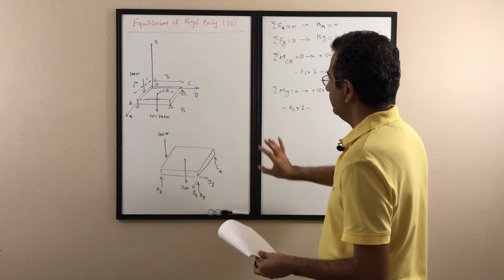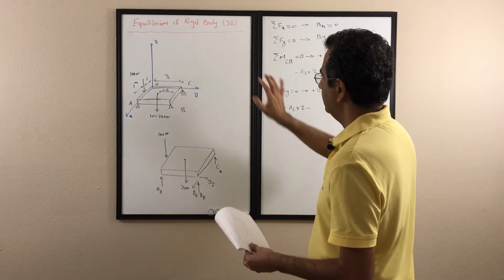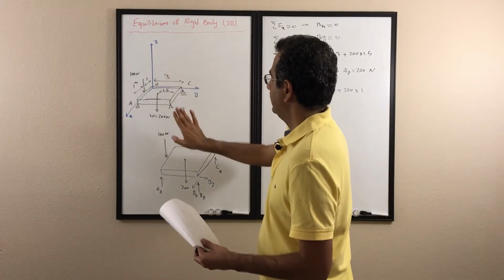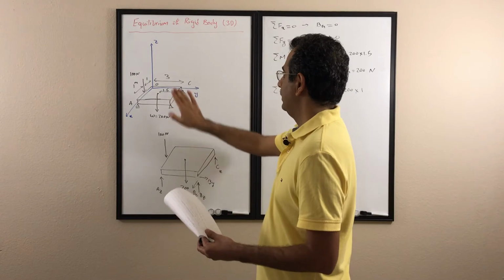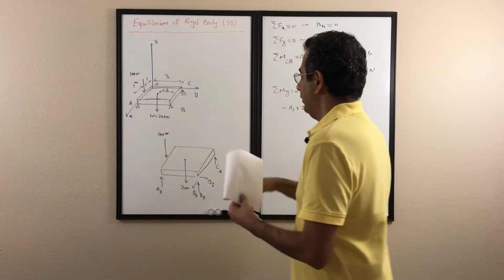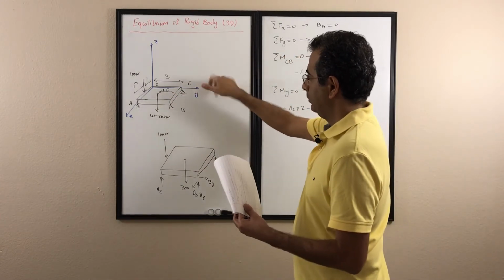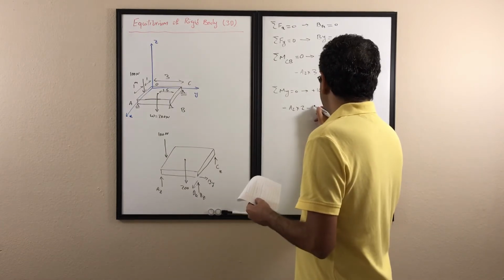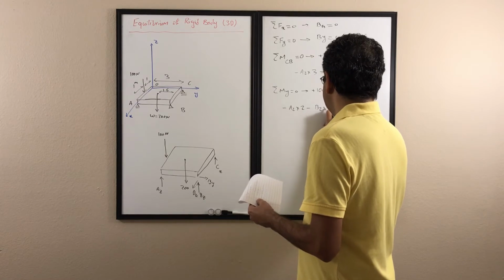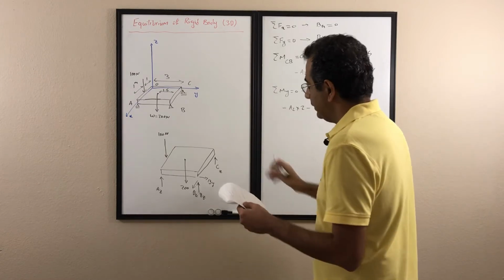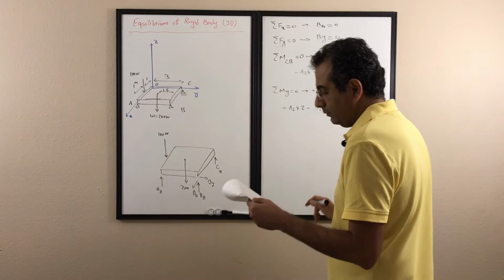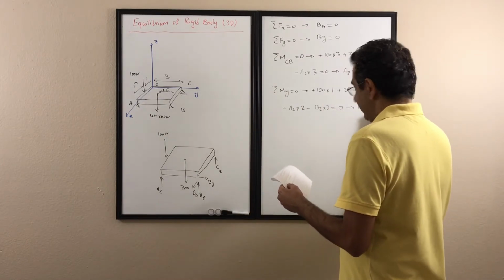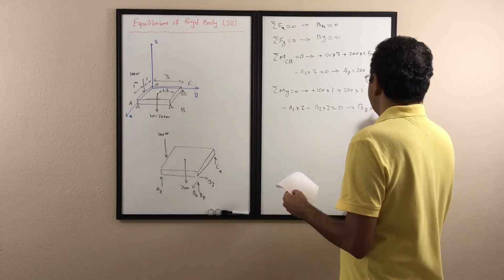Assume B is fixed at the y, so it rotates like that about the y, and by the right hand rule, my thumb goes against the y-axis, so again negative, and the distance is 2, the same. The sum is 0, so the BZ would be negative 50 Newton.